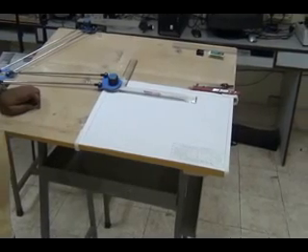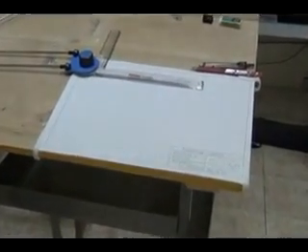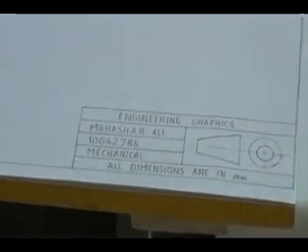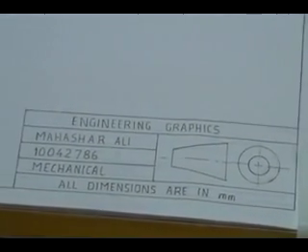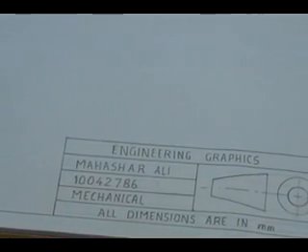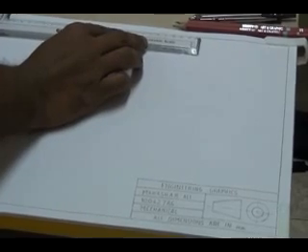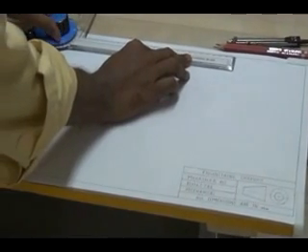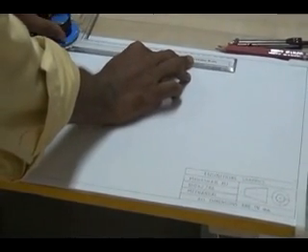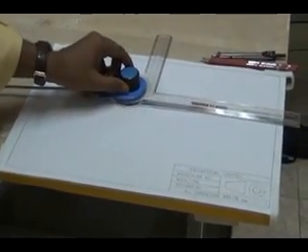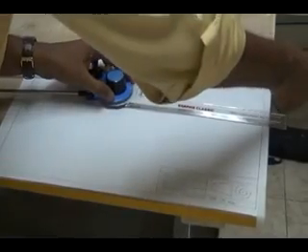See, here what I am doing, the drafter is there. See, the title block should be like this. When you are bringing your drawing sheet, the title block should be, you see the parallel lines are not visible. So only the letter should be printed neatly. What I am doing there, you have to fix your drafter to your reference line. That is nothing but your layout line. The layout line, what you have, that is going to be your reference. From that reference I am bringing my drafter. So I am fixing my drafter to that reference line.